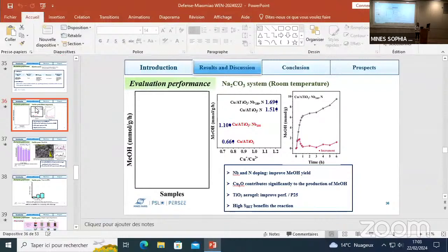So probably try to get the apparent density of your material. I know that it is difficult because it is a divided material. But there are for sure some techniques which permit to evaluate, to guesstimate the density of granules. And this permits, for instance, to have a view of the specific porous volume, and you can compare with your BJH volume, and maybe you can see that there is a porous volume which is lacking.